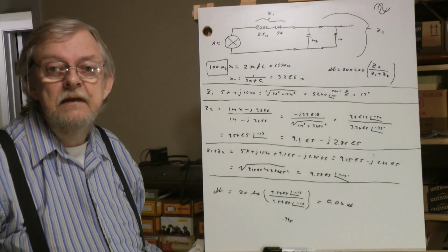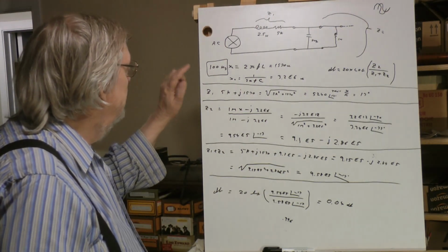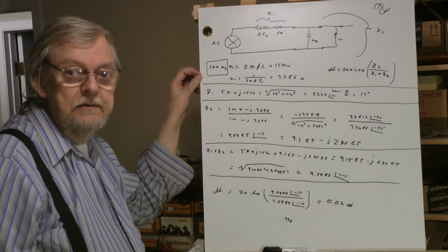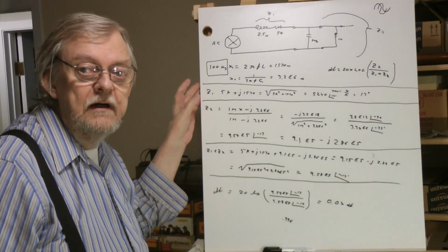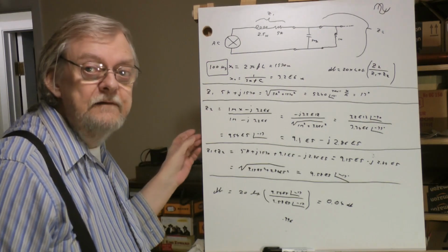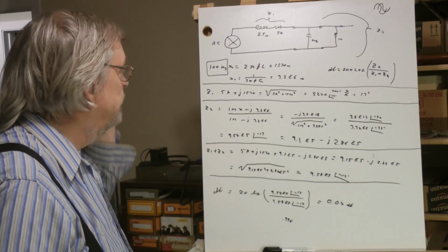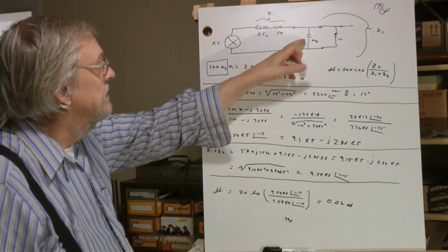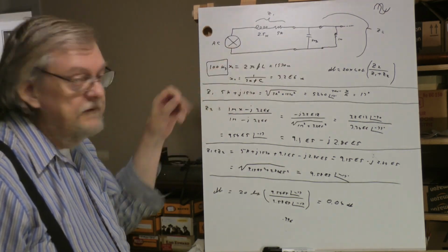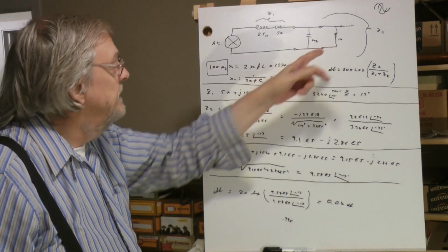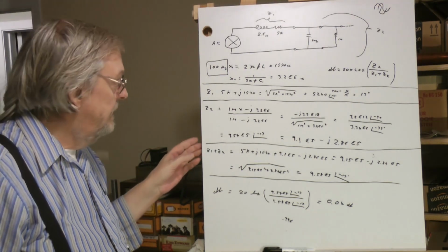So next step is to make a spreadsheet, put this formula in, plot all the frequencies from 100 up to about 10K or so, and have the computer draw a graph, and then we'll take a look at the graph and we can see what it looks like. We'll be able to change values, be able to change our capacitance in the spreadsheet, be able to change type of pickup, parameters, impedance of the amp, everything, and draw charts for anything we want.